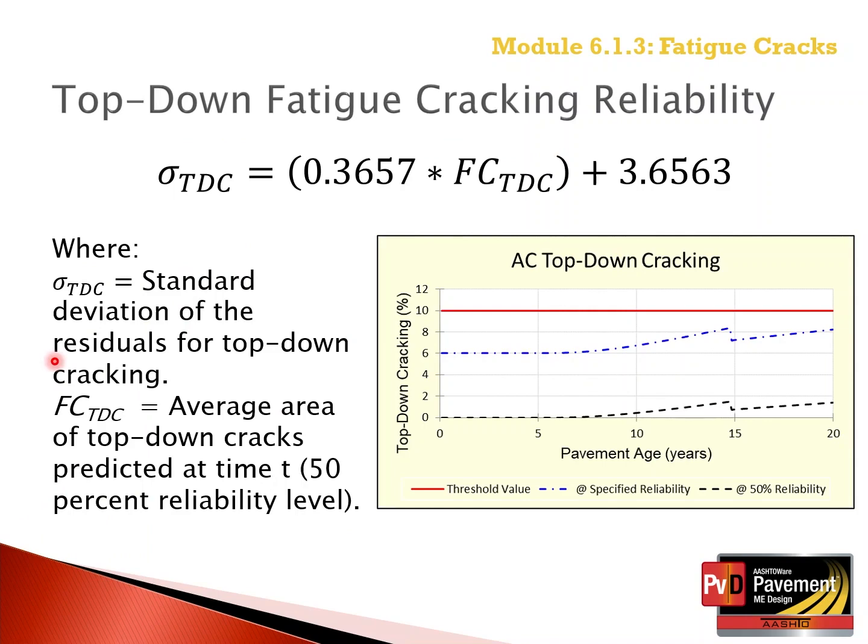Reliability was discussed in detail in Module 3 and how it is applied in the Pavement ME design software. The standard deviation of the residuals of the area for top-down fatigue cracks is displayed on this slide. The standard deviation of residuals is used to determine the reliability as related to the area of top-down alligator cracks